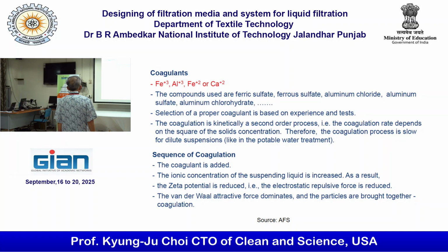The coagulants are all inorganic materials, especially Fe, Al, and Ca. The compounds used are ferric sulfate and ferrous sulfate, aluminum chloride, and aluminum sulfate. Selection of the proper coagulant is based on experience and testing.